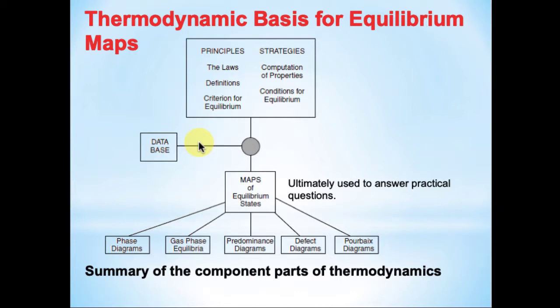For example, there are no composition variables in a one-component system, in this case a unary system, while heat capacity, coefficient of thermal expansion, and compressibility are sufficient to compute the rest of the properties of such a simple system.